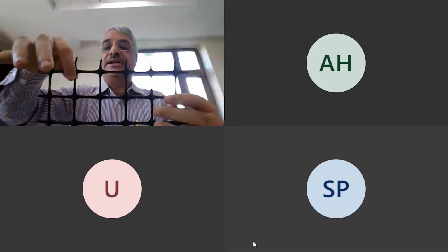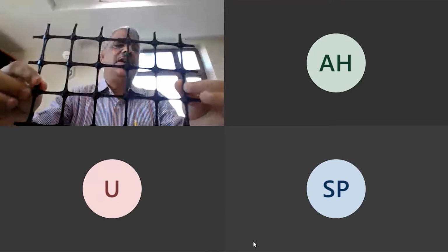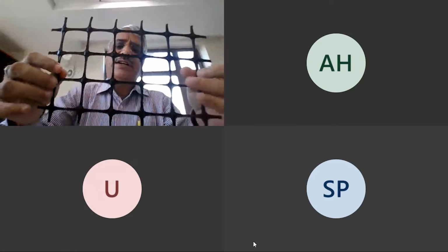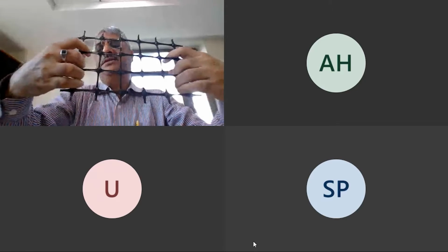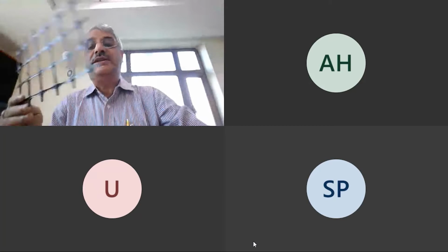Biaxial, there are various varieties. This is made by the extrusion principle. So biaxial extruded geogrid, and they come in different tensile strengths: 50 kilonewton per meter, 80 kilonewton, 90 kilonewton, like that, depending on what the design is.